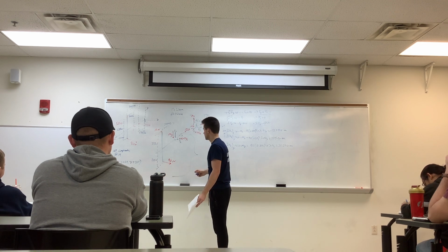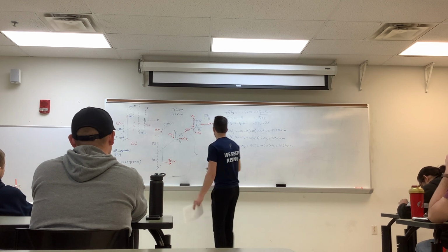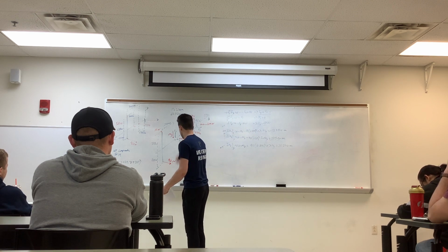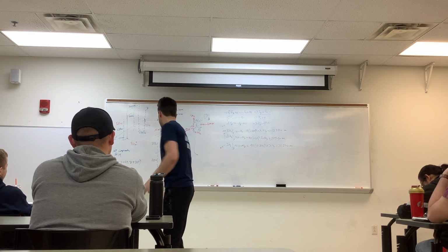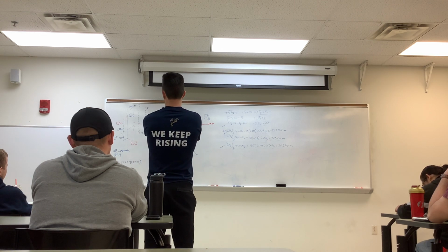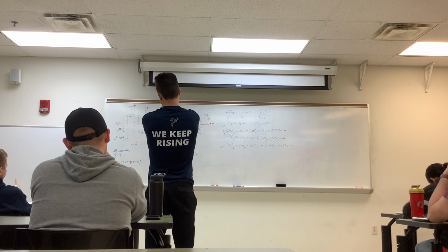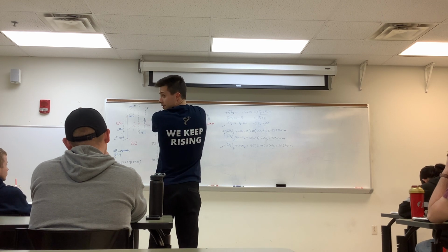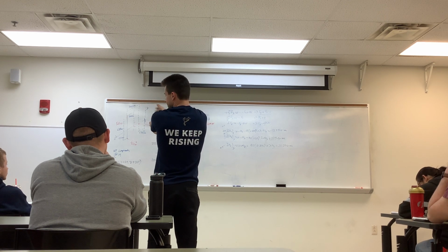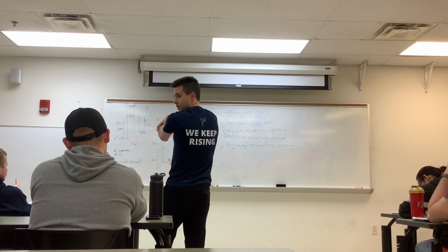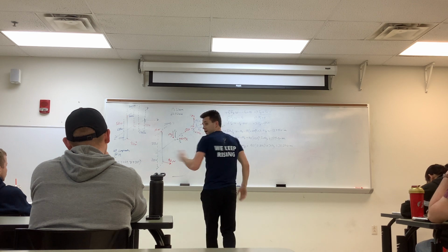So for when you drew it as y in his free body diagram, when he split them, that's the assumed direction. Thumb in that direction, curling it, this 55 kilonewton force is only pushing on it, and not causing any kind of moment or rotation. Did it help explain a little?